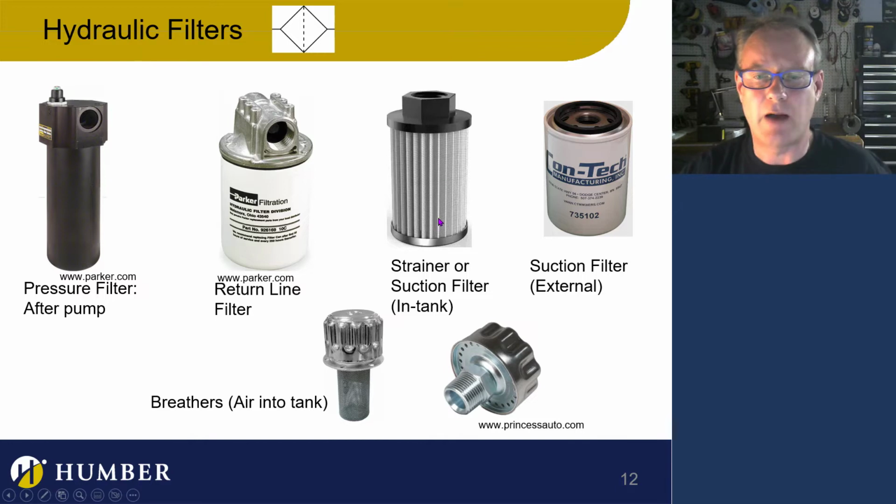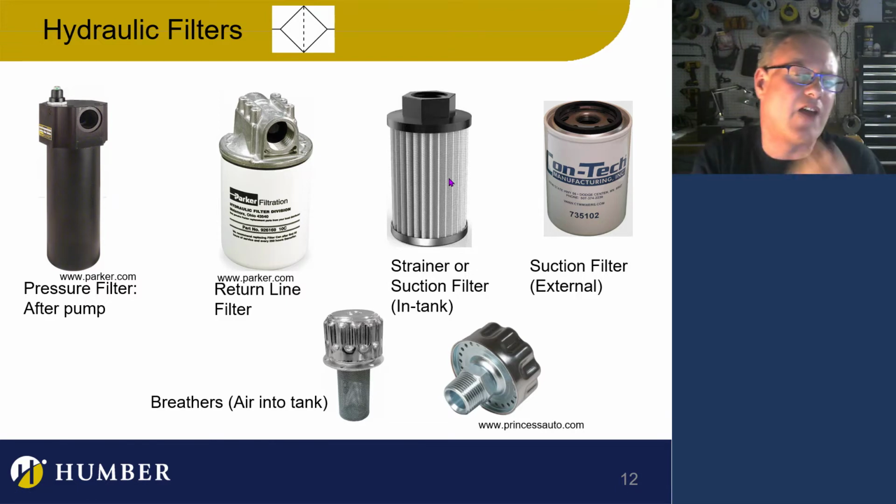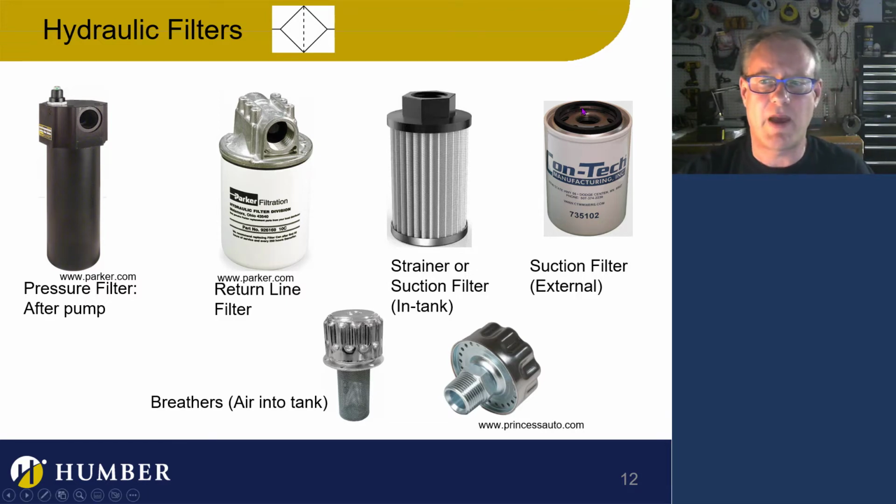We should do that. Now, this strainer or suction filter is, again, underneath the fluid in the tank, but you can also get a suction filter that's external, right? You can have two of these suction filters. You can have a filter that's inside the tank, which we call a strainer, and then we have an external suction filter as well. But usually you'll see either one or the other, and this will be outside the tank. There you go.